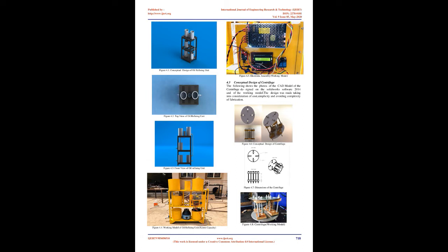Mixing with kaolinite. The separated base oil is mixed with kaolinite in appropriate ratios. For 2 liters of used engine oil, 80 gm of kaolinite is used for a period of 1 hour, and it is then allowed to settle for a duration of 30 minutes. Kaolinite is added to remove the dark color and smell, which result from oxidation of some components of the oil.